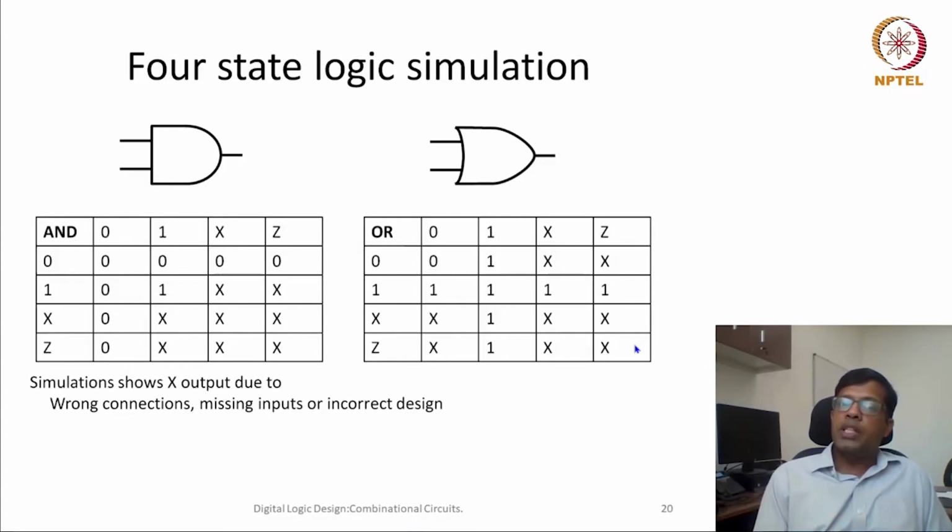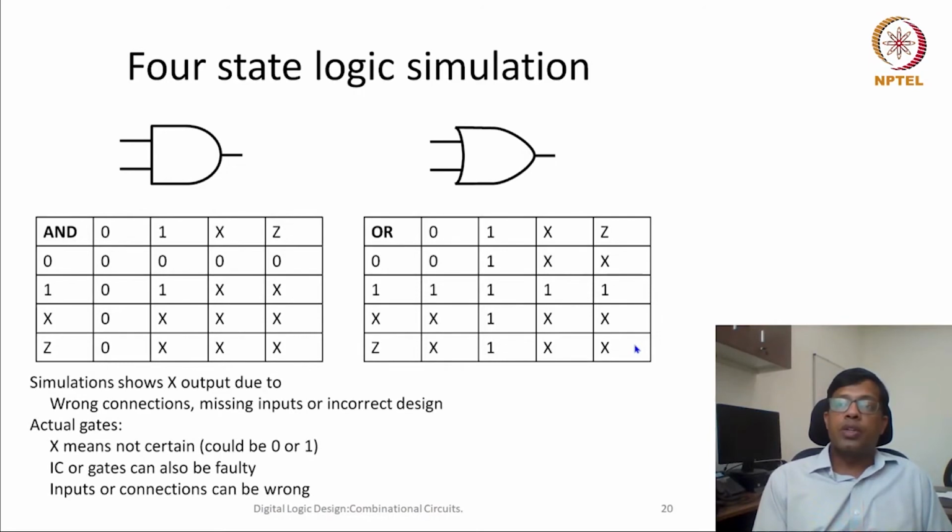However, what would happen in the real circuit? Let's say you are trying to design something on PCB or on a breadboard, and you are putting such kind of wires. What would happen? Wherever your Verilog simulation is showing X, in a real circuit there could be a short circuit, your circuit could fail, the circuit could burn.